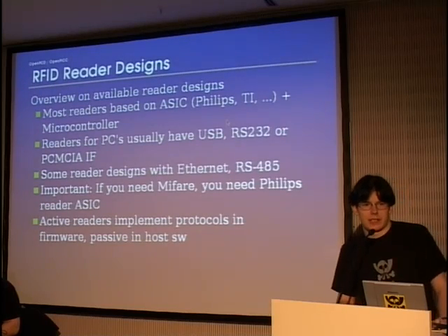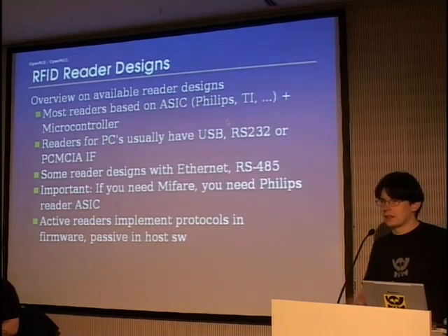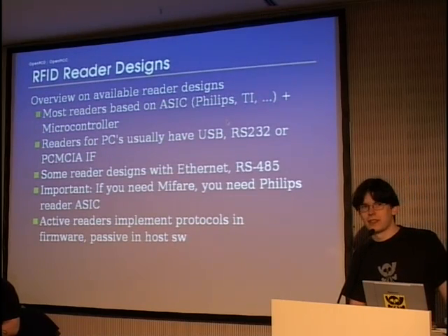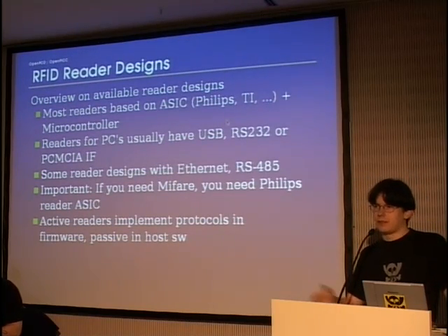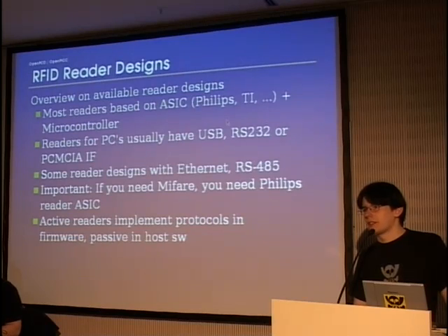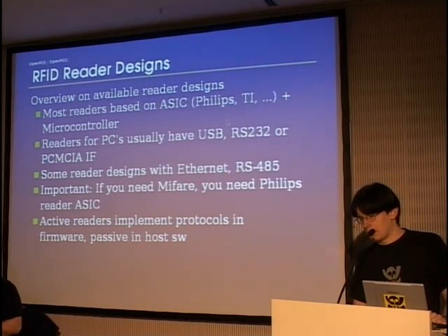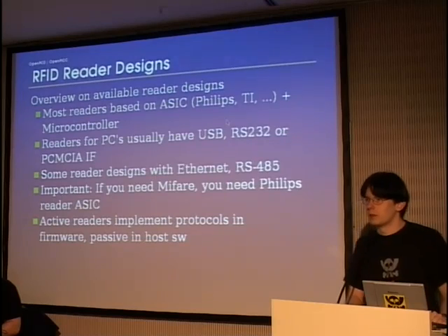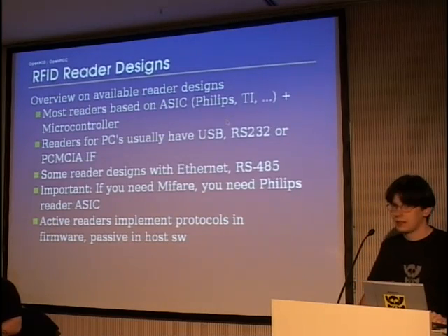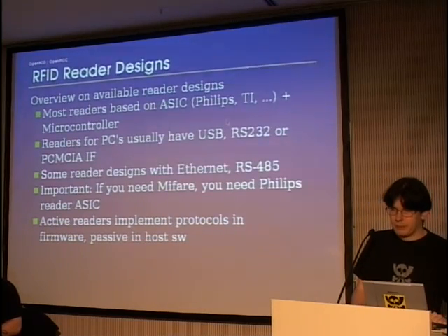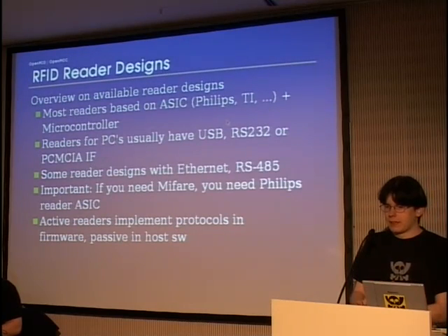Most of the readers that you can get, or that I've found, are active readers, which have some or even all of the RFID stack inside the device firmware, and a smaller number of them, most notably the OmniKey 5121 and 5321, I think, implement the RFID protocol stack in the host PC.